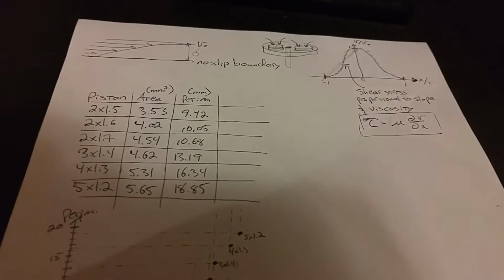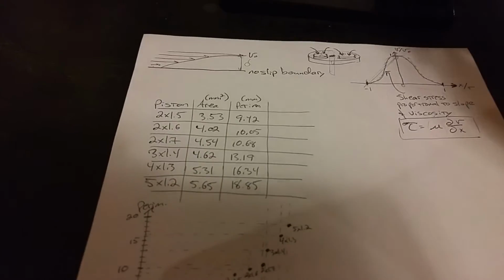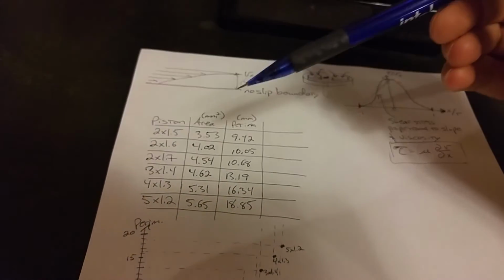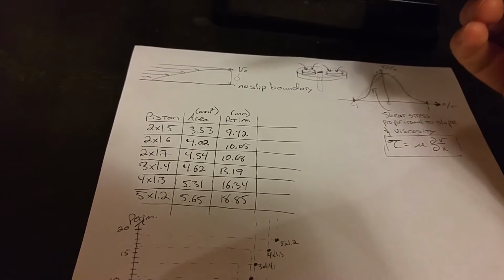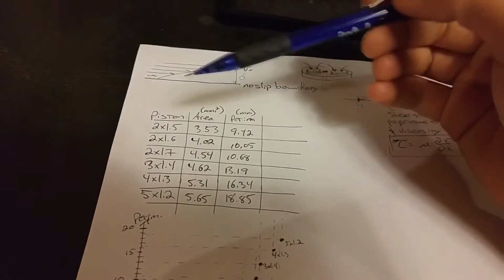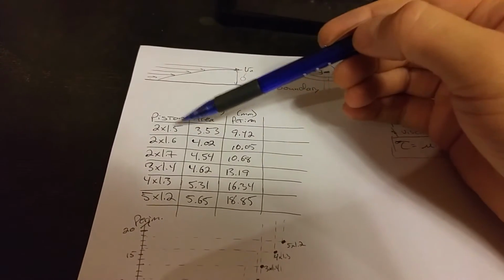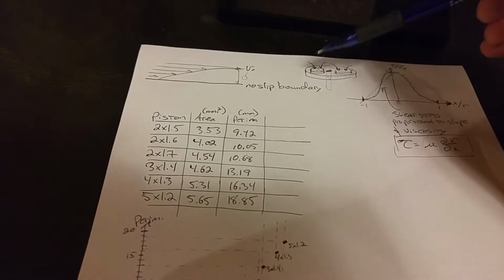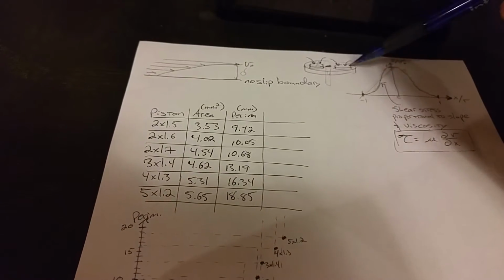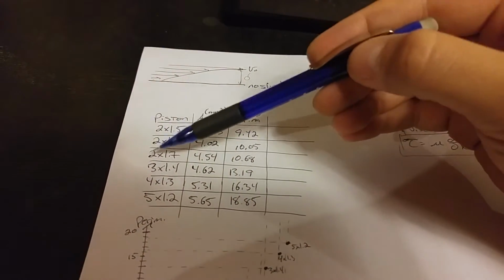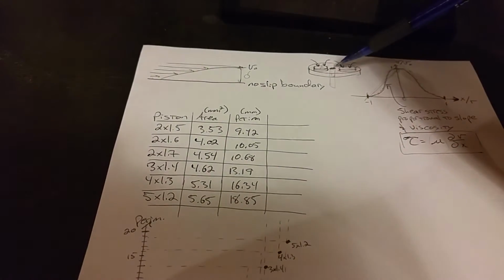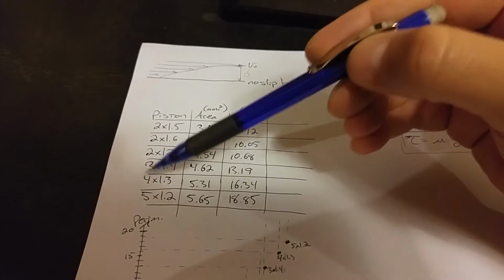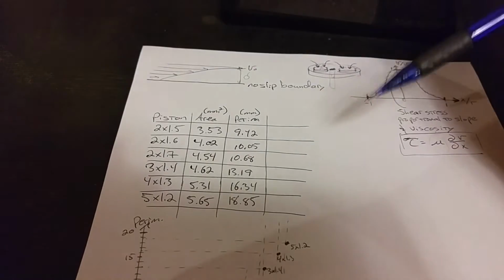If you look at 1/10 scale big bore shocks, whether it's Kyosho or Team Associated or Team Losi, they generally offer substantially the same menu in the types of shock pistons. So you can have a 2x1.5 millimeter hole, meaning two holes that are 1.5 millimeters in diameter each, 2x1.6, 2x1.7, and then you can have three holes by 1.4, 4x1.3, and 5x1.2.